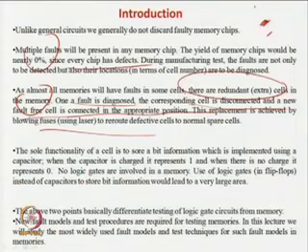So, the first philosophical difference is that you have to diagnose the fault as well as detect it, which is not the case for sequential and combinational circuits. Secondly, you also have to repair. There is some redundant part of your circuit, so you have to repair this as well.